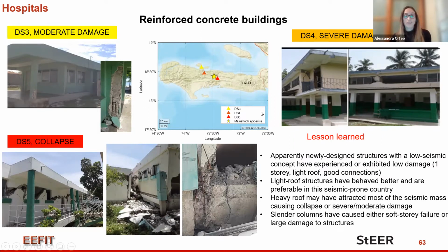such as if we look at the severe damage example, the columns, there is severe damage between columns and beam columns joints, and this compromises their vertical carrying capacity. These buildings did not collapse, but it sustained the very severe structural damage in the second floor level. The collapse case actually show that in the ground floor, there is a completely loss of vertical carrying capacity, leading to a collapse of that story. So this is one of the most common example of what we can call soft story collapse.